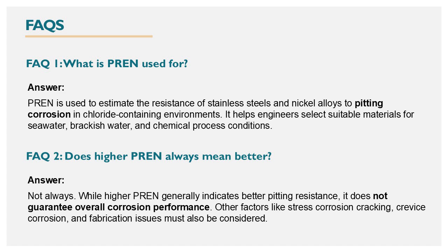Question number 2. Does higher PREN always mean better? The answer is, not always. While higher PREN generally indicates better pitting resistance, it does not guarantee overall corrosion performance. Other factors like stress corrosion cracking, crevice corrosion, and fabrication issues must also be considered.